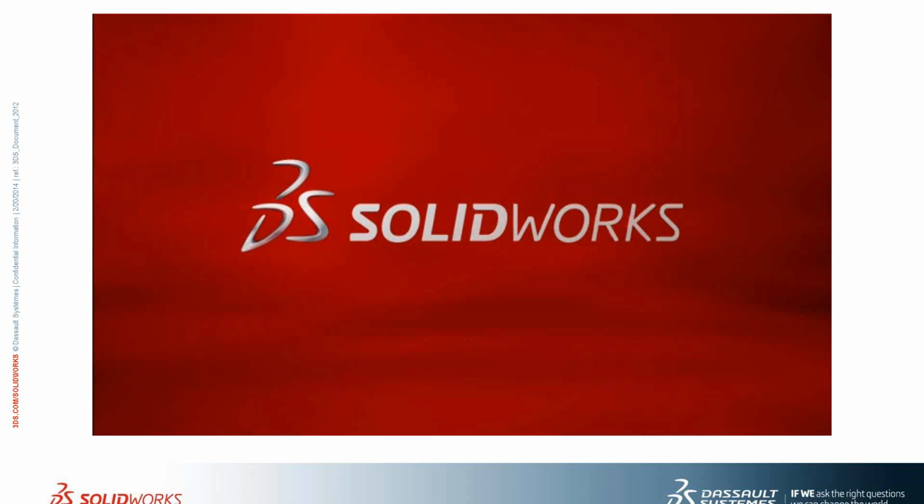So at the end of the day, once you have the complete electrical design, the information can channel into the electrical 3D, where you have the machine design done and your enclosure well organized. The next thing is just drag and drop to place the 3D components into your existing machines. From there, the software will automatically create the wire path, and you can create the drawing like what we did in SolidWorks.